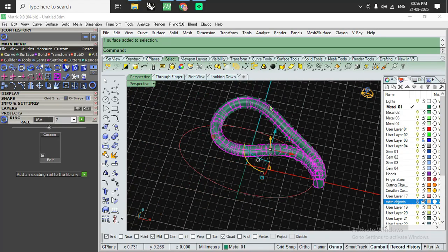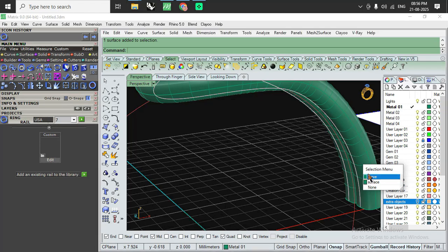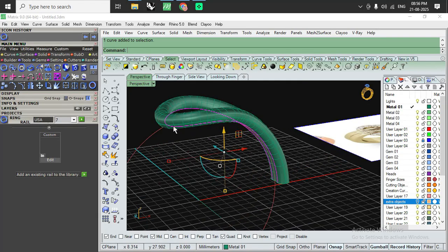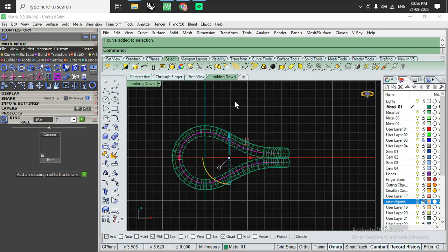We can either rotate this similar profile here, or we can use this curve profile here. The curves are not similar at both the ends. So let's use the curve, because if we create the curve and then apply sweep 1 afterwards, it will apply the change to both the profiles. Okay, so let's go to top view and go to rotate.